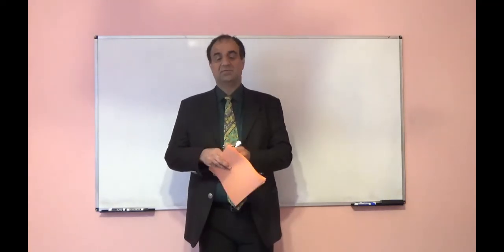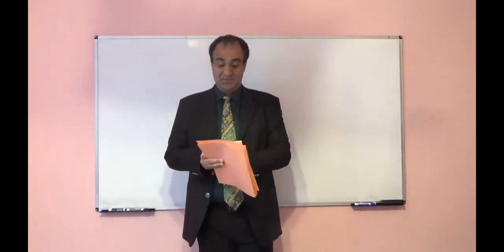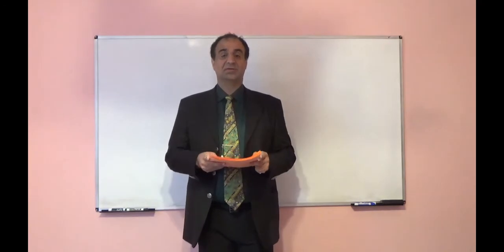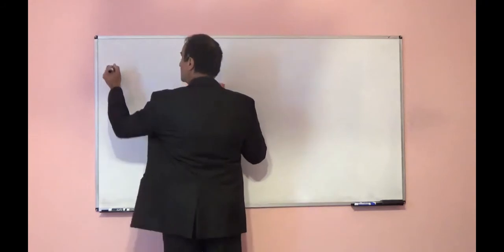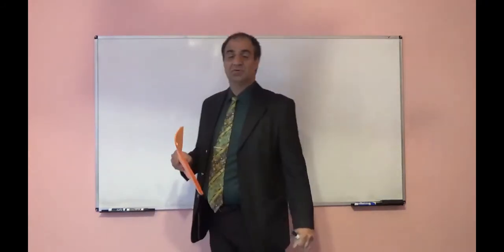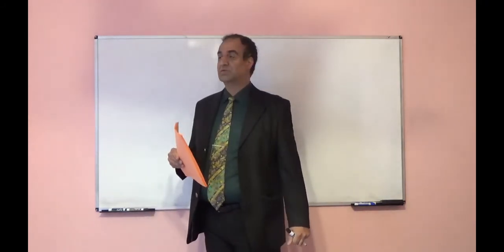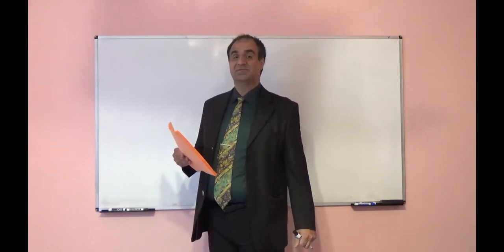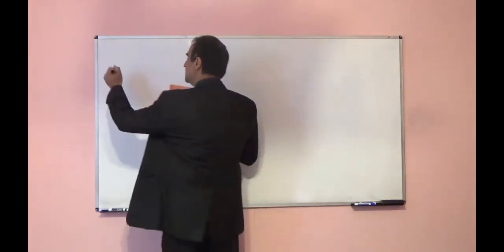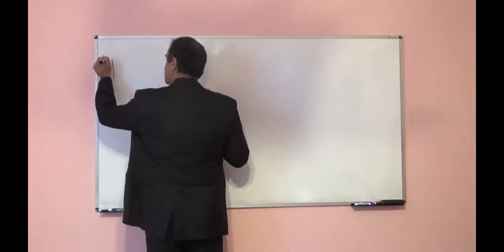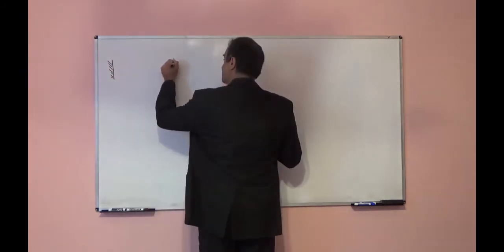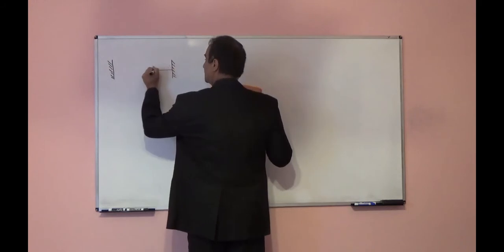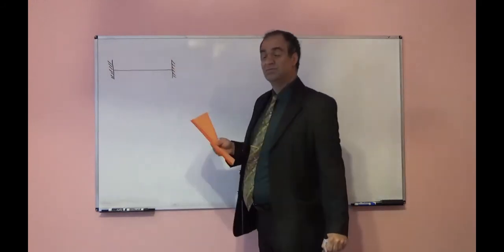Today I will review several examples. We will solve these problems using the slope deflection method. In order to solve a problem using the slope deflection method, first I should find the fixed end moment. You can look at the table in different textbooks. You can find a table for this, but some of those are very important. It is good if we memorize them.